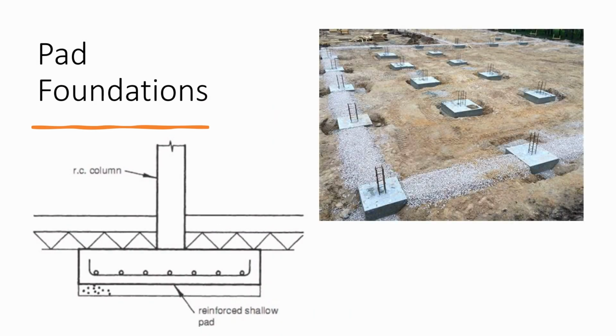We have the pad foundations, and these foundations are shallow foundations that take the spread of the point loads to soil safely. The pad foundation is supposed to spread the concentrated load safely to the bearing stratum. Hence, pad foundations must be designed stiff so that uniform spreading of the load to the soil happens without making the foundation pressure exceed the permissible bearing stress. This requirement is achieved by either reinforcing the pad or making the pad deep. Both methods help to spread the force in a predefined angle.